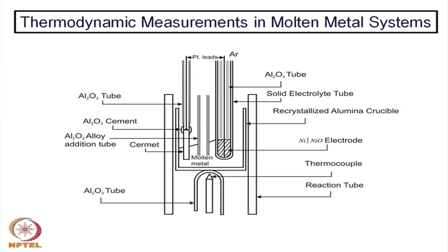Again, the purpose is primarily to control the combustion, so that you get the complete utility of your fuel. There is no excess oxygen or excess air in the system. So, in automatic control of ceramic kilns, these sensors become quite handy, and most of the modern furnaces are fitted with this kind of sensor, so that the fuel combustion process can be controlled quite efficiently. So, that is another area where, besides automobiles, there is a huge application of Zirconia oxygen sensors in combustion control of industrial furnaces.